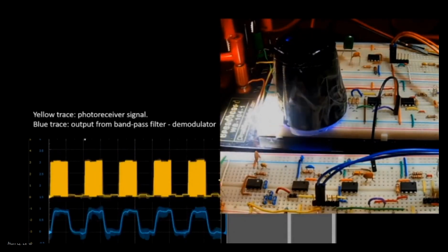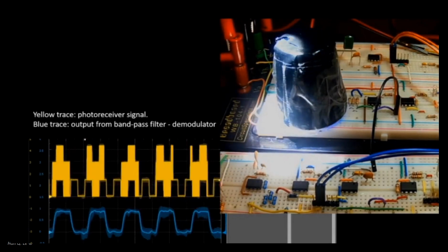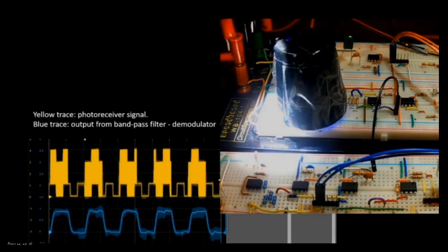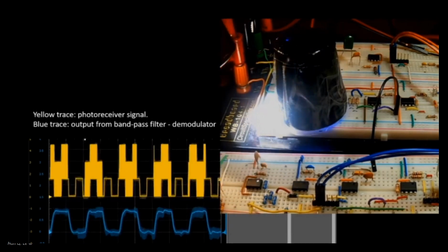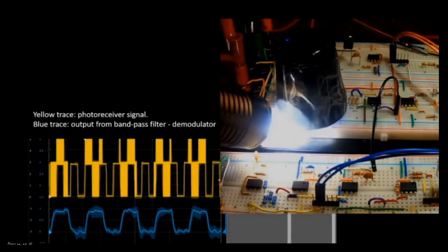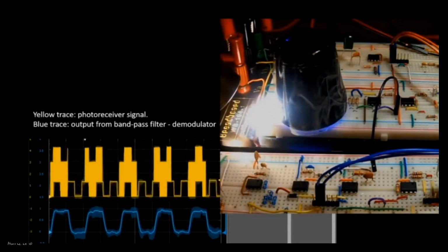The flashlight varies its average light output by generating pulses of different duty cycles. The modulation is 250 Hz. As can be seen, the flashlight pulses were filtered out by the bandpass filter of Lab 6. Here, the example shows that this Lab 4 simplistic optical receiver is useful for this demonstration.